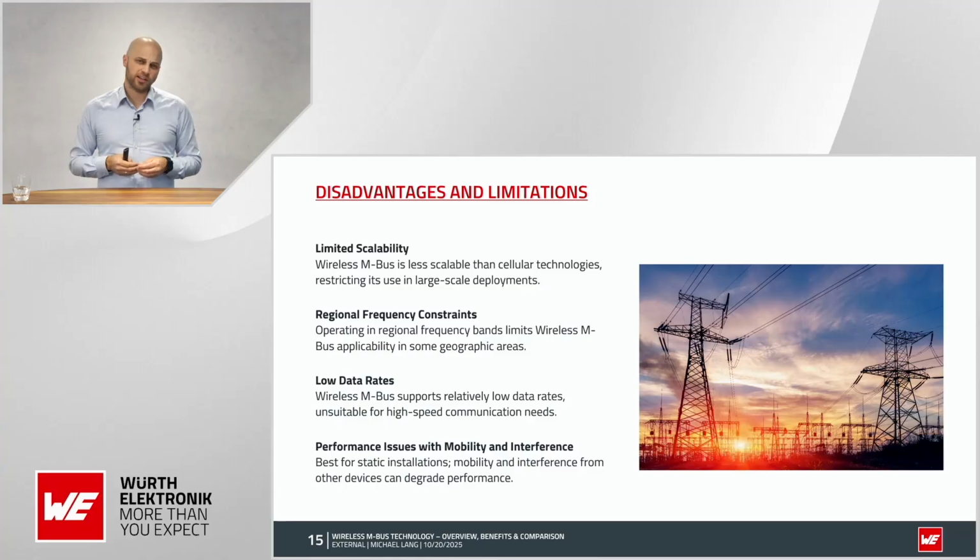Also, the data rate is one point. You don't have the tremendous data rates you have with Wi-Fi or also with cellular applications. The reason for that is, of course, that wireless M-Bus was always made for meters, so you only have to send very little data. It's not made for big data amounts, and this is something you also have to keep in mind.